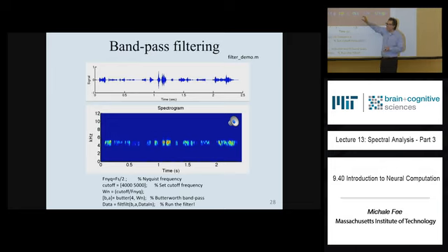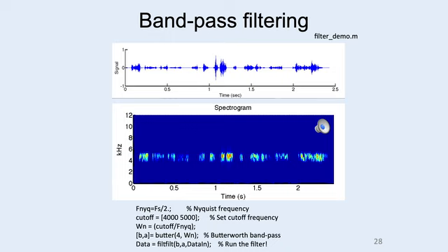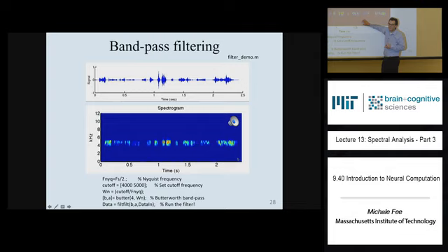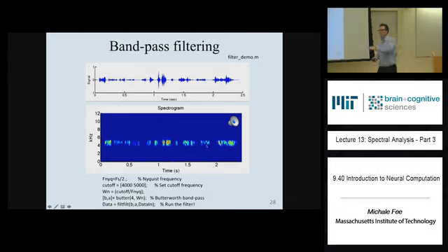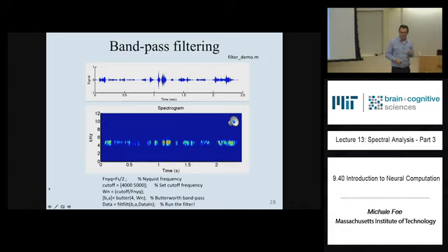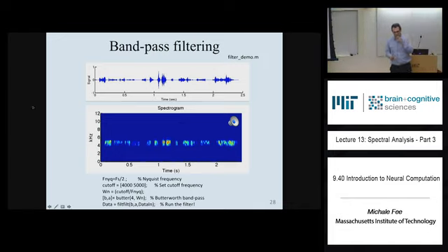So then you would run a bandpass filter over a 2 kilohertz band, and now you'd get a big signal whenever that formant passed through that band. And then you would send that to an amplifier and play a noise burst into the person's ear. We do things like that with birds to find out if they can learn to shift the pitch of their song in response to errors. So yes, they can.